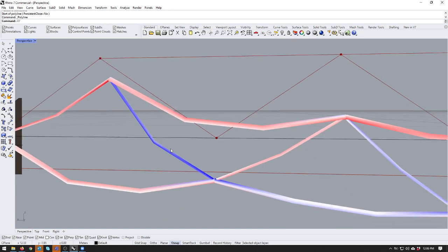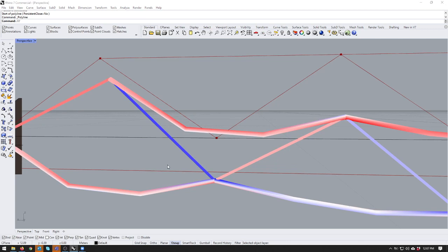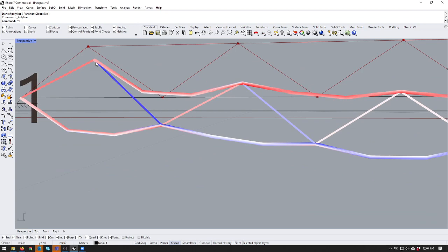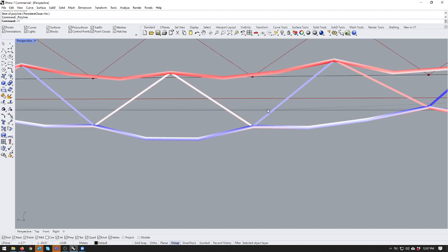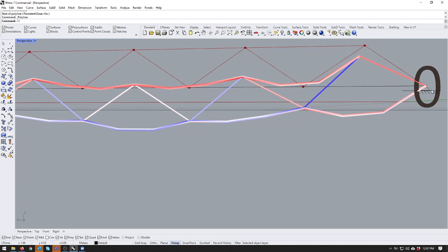So by us turning off the bending moment on those elements, we're actually also turning off the fact that that element can bend, right? So therefore they go straight. They can't be anything other than straight. They will not bend. And that is because we are inferring that if they have pin joints on either side, those pin joints allow that element to rotate rather than bend to be able to apply forces. So we've now got an element running through here that is purely in tension, and an element that is purely in compression. Am I right? Yes. So this one's in compression, tension, equilibrium. Then compression, tension. You guys can see that?